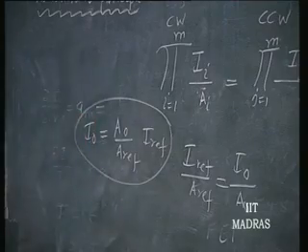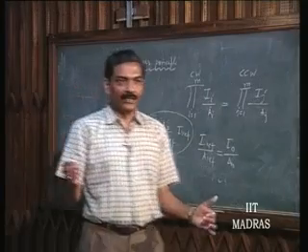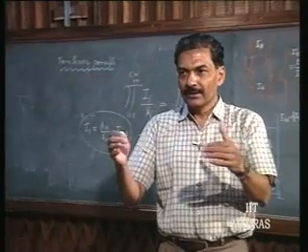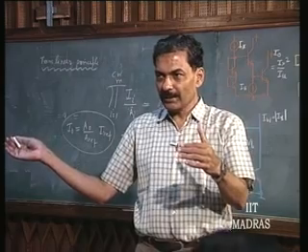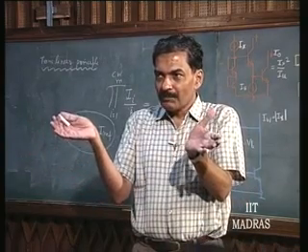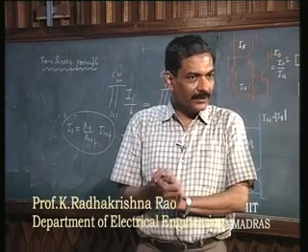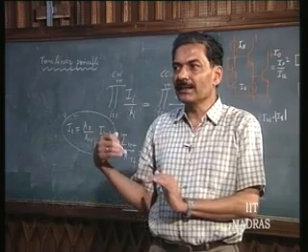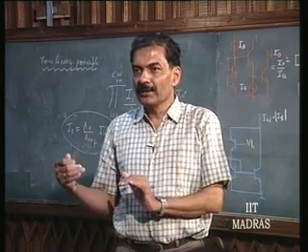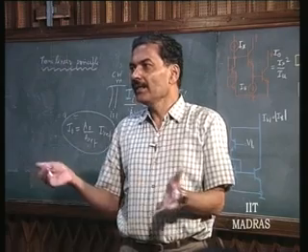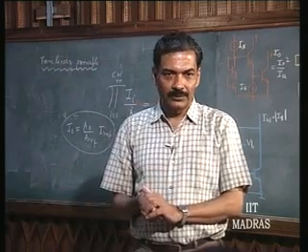So, we have shown what we have earlier indicated using circuits. We had seen this current mirror, wherein we had paralleled the current sources and shown that it is a ratio of areas, but here now mathematically we have indicated clearly it can be made a fraction or any number you want.